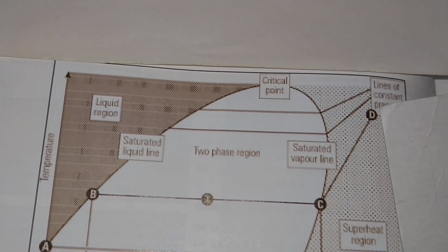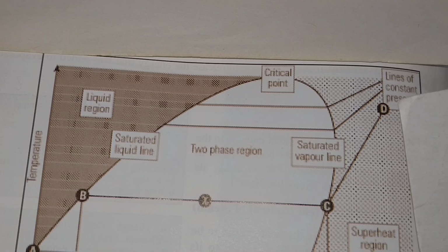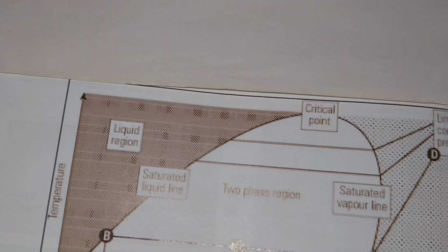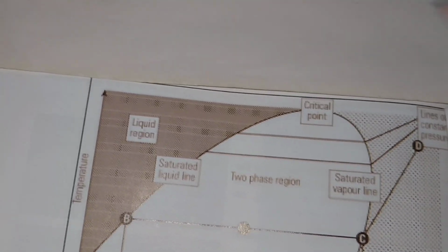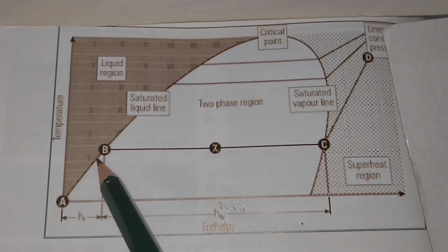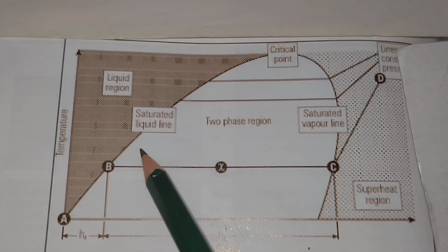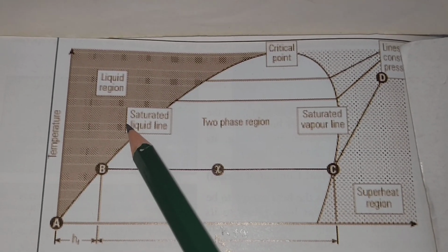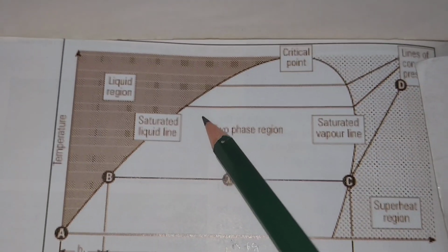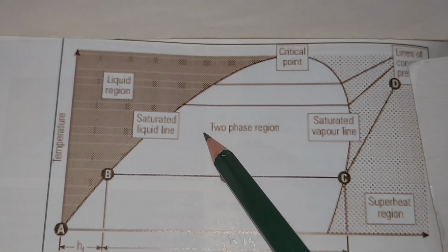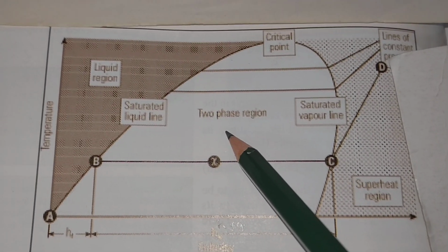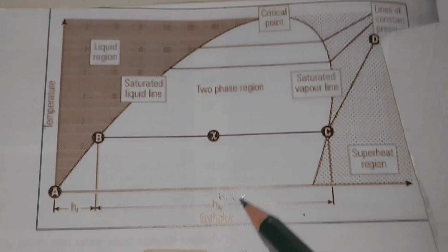As water is heated from 0 degrees centigrade to its saturation temperature, its condition follows the saturated liquid line until it has received all of its liquid enthalpy, hf, that is A to B. If further heat continues to be added, it then changes phase to saturated steam and continues to increase in enthalpy while remaining at saturated temperature, hfg.